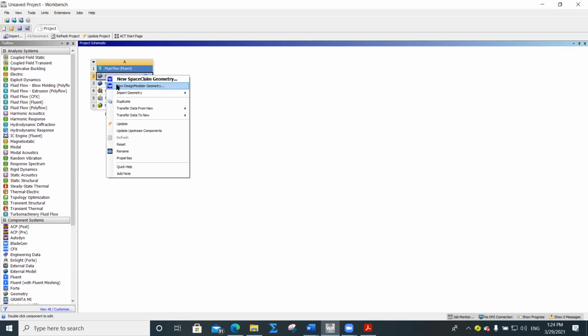You can model the basic geometry here. But if you have complex geometry, like, for example, our problem for the Hyperloop or the problem for Sayyid Ahmed for the wind turbine, it's better that you model your problem in SolidWorks or in another CAD environment, and then you import your case into ANSYS using the import geometry method. In import geometry, you can browse for an extension, for example, a STEP file or IGS file or SolidWorks file or CATIA file, the CAD model.